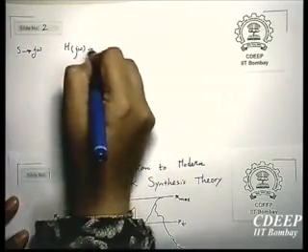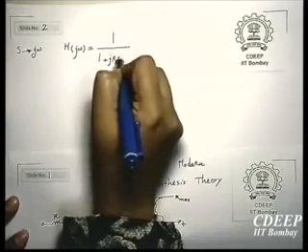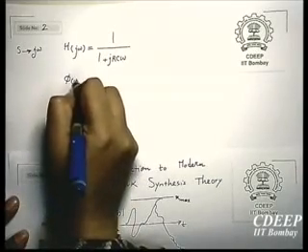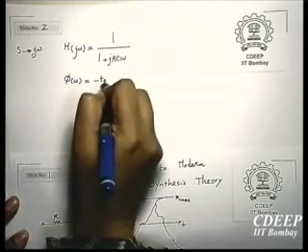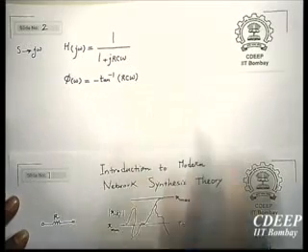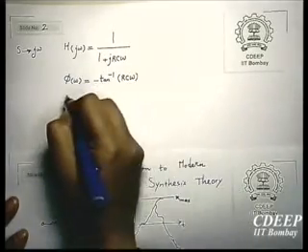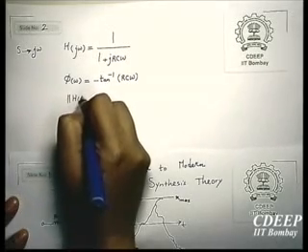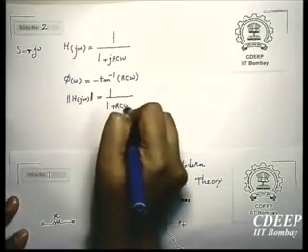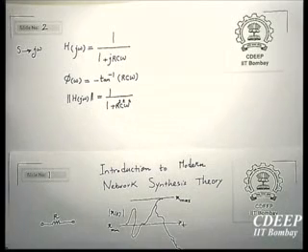So we will write transfer function. Okay, so magnitude will be one upon square root of 1 plus RC omega square, and the phase will be minus tan inverse RC omega.